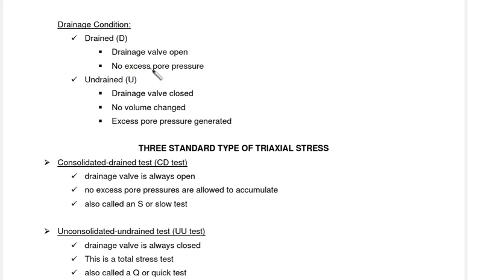To ensure that this is the case, we must run the test very slowly, to ensure that no pore pressure is generated during shearing in our drainage condition of drained.